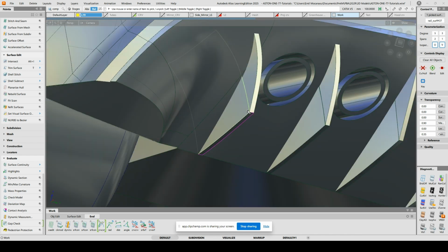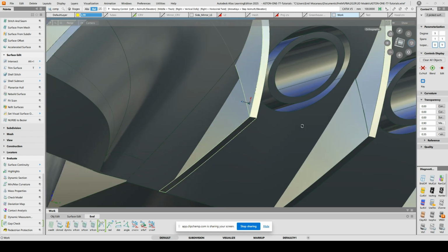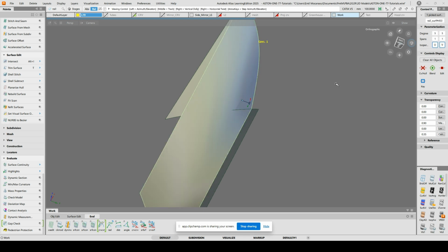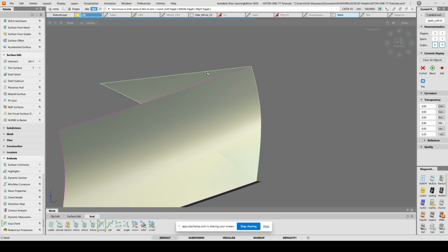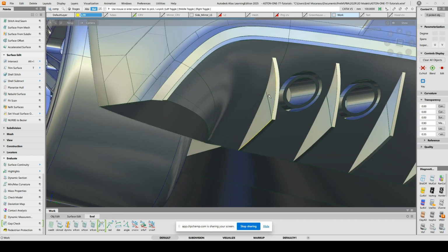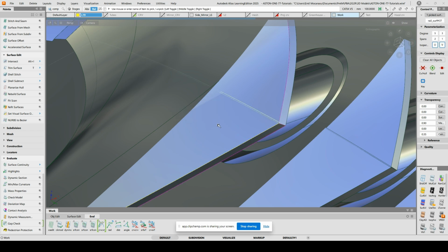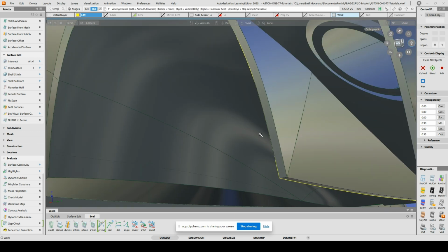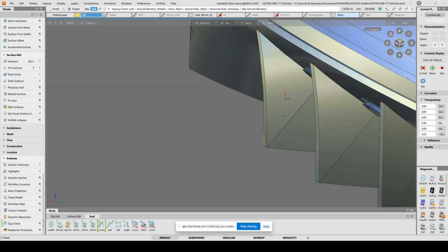I don't need that surface anymore. Or I'll template it. I'll take these two and see what I can generate there. That's a monorail, what I'm looking for. That along that there. It's actually even better from a technical point of view. It's easier to take it out of a mold. So that's one there. A clean surface, that is. So that's something we can do straight away and get that thing closed up and nice and clean. Because I want to avoid extra patches.